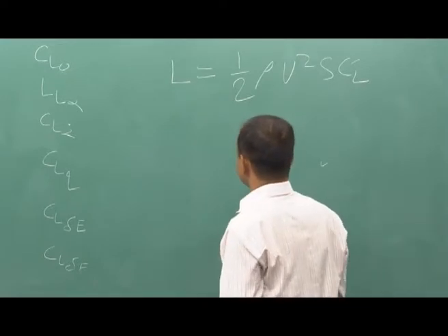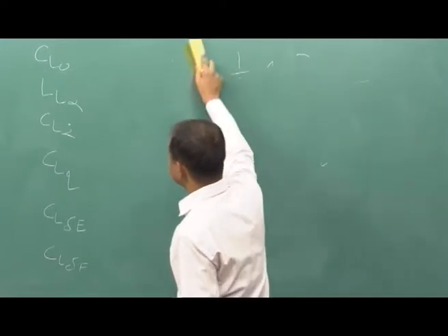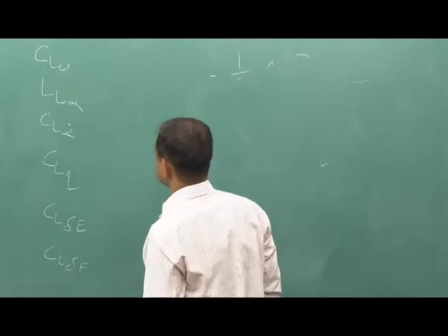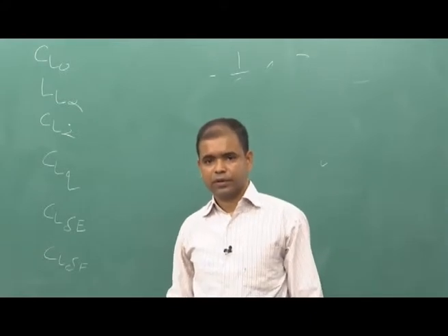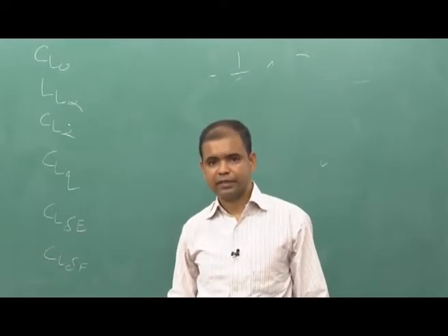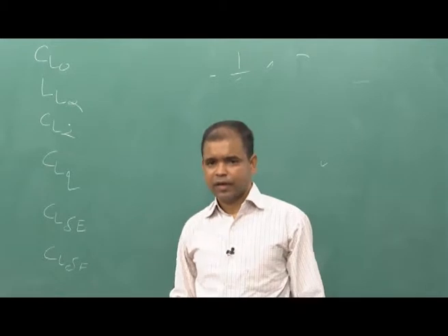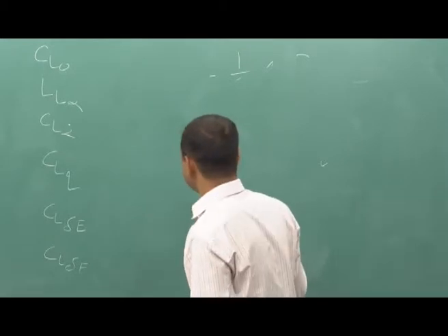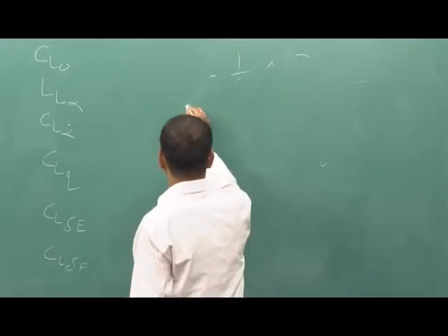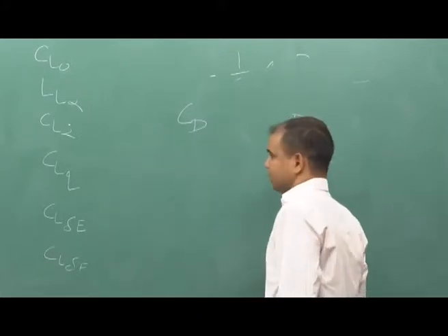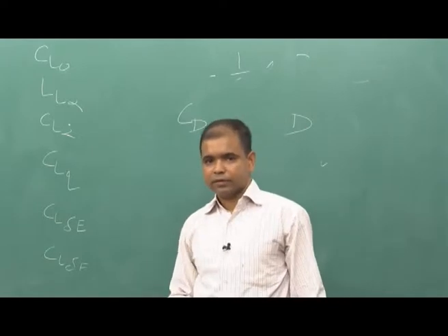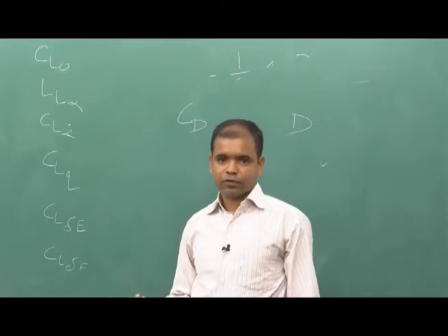Similarly, you have all the drag coefficients, you know the CD naught, CD alpha, CD alpha dot, CDQ, CD delta F, CD delta A, CD delta R, and all other remaining coefficients, and from there you can find the CD, and once you know the CD you can find the drag, and you can find the Y forces also acting on the aircraft.